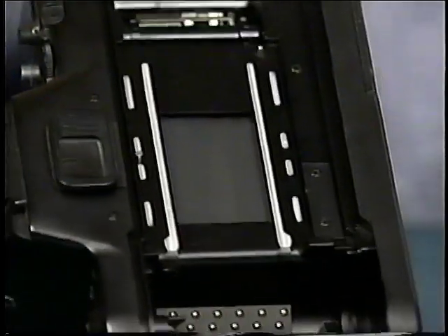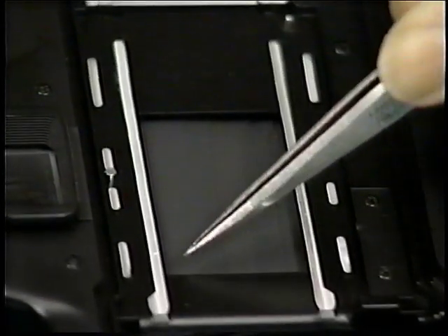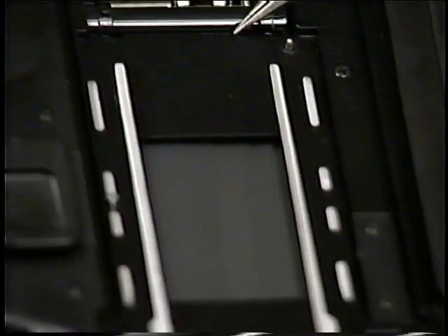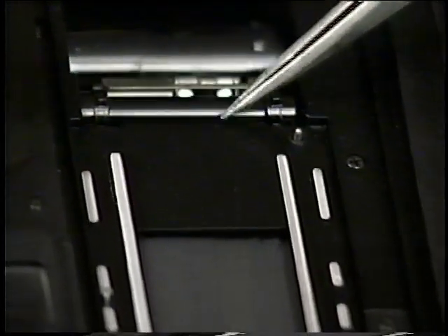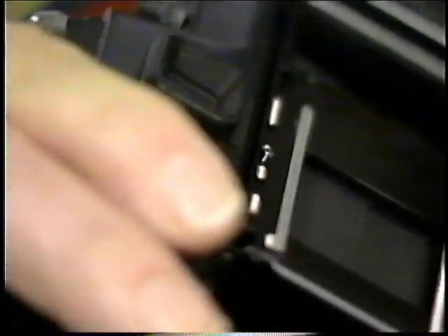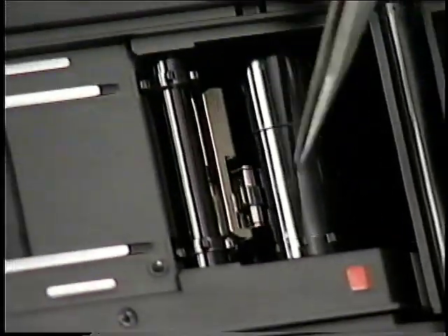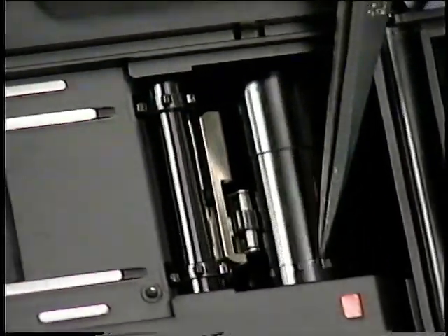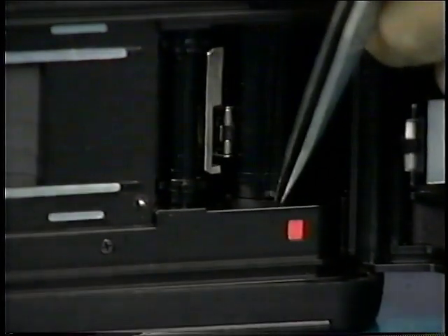Another place to look is inside the film compartment. If there's any loss of blackening right here at these edges, where the edges of the film aperture are, or where the film would turn the corner going to the sprocket. If there's any shininess or bright metal, then you know it has a lot of wear. Also, look for film chips and film emulsion in the film compartment, particularly on the take-up side, here toward the bottom. If there's any film emulsion piling up in here or chips, again, that's another sign that the camera has had a lot of film through it.